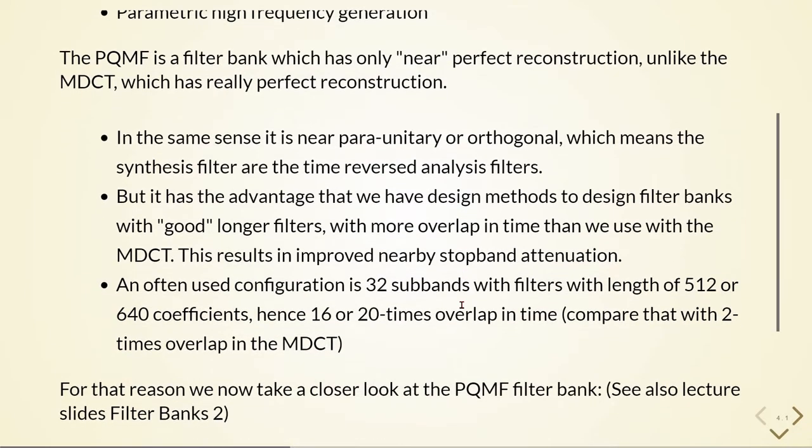filters. But it has the advantage that we have design methods to design filter banks with good longer filters with more overlapping time than we use with the MDCT. This results in improved nearby stop band attenuation.